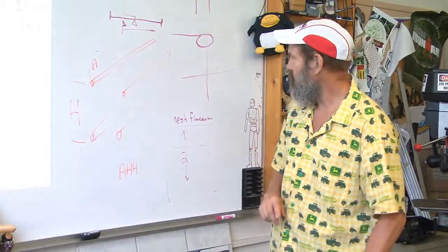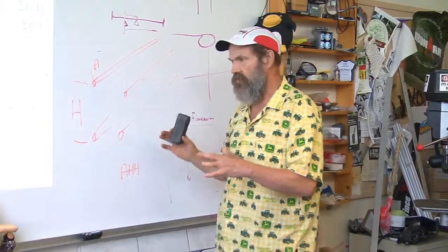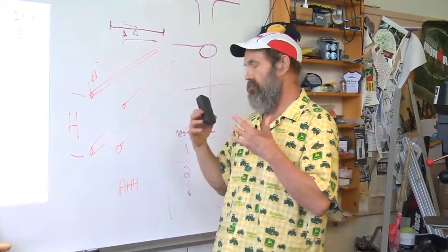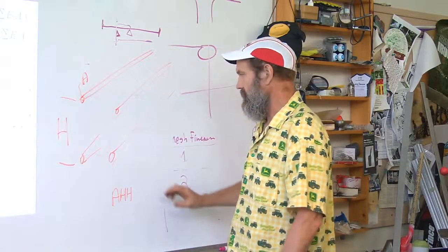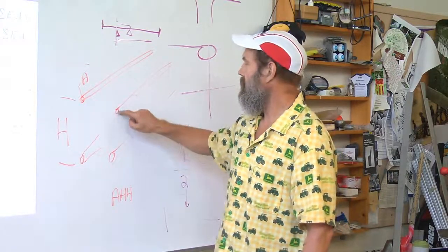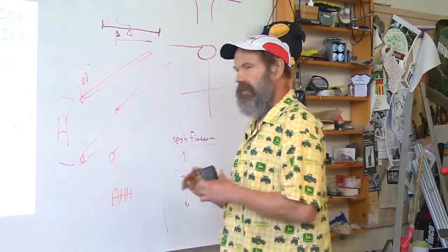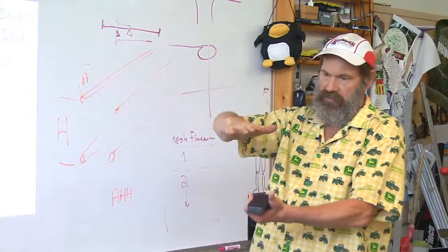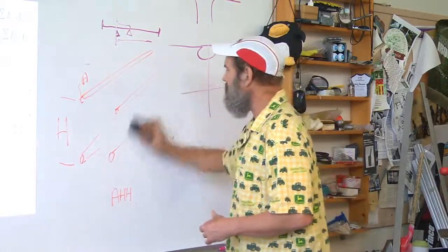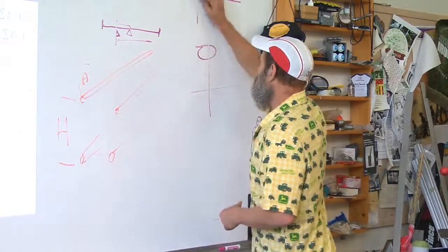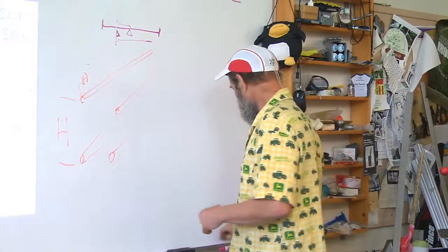So remember, for initially laying out your estimate of the strength and the stiffness of the truss, you can use your estimate of the moment of inertia based on the cross-sectional area. That lets you lay out your machine in terms of the size or depth of the truss. Now, when you go to design the details of the truss, you do the following.